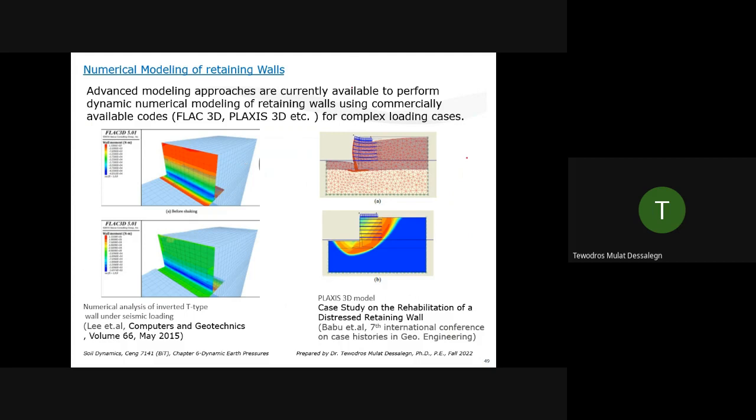That's what's commonly done in most cases, but people usually use both the pseudostatic approach and the dynamic approach, and compare the results to make sure that the results are comparable. In some cases, you may find the dynamic approach gives crazy results. There's something which doesn't make sense, which means something may be wrong, either in the input motion or in the model itself, errors. To avoid that, make sure you compare it with the pseudostatic approach and make sure you have a reasonable model.